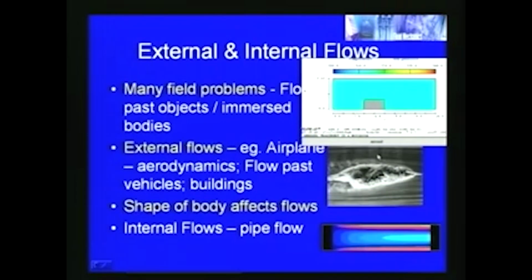And then in this case you can see that the fluid flow surrounding a bird creates a boundary layer. Also, in this typical case, whenever the flow is taking place over a block, the fluid flow will be coming like this, and this solid is always not moving. So there is a no slip condition here and a boundary layer is created.